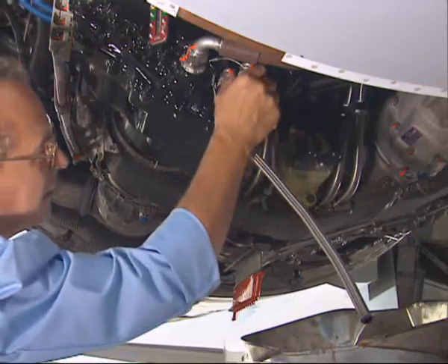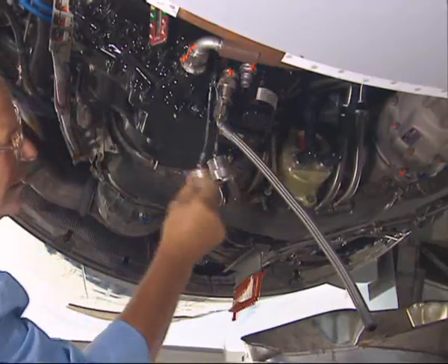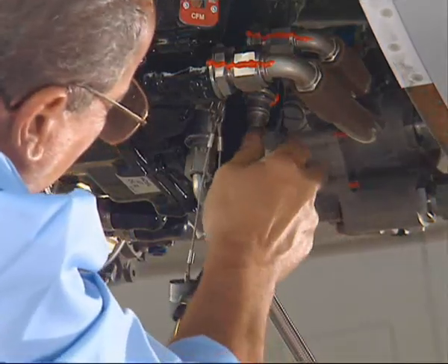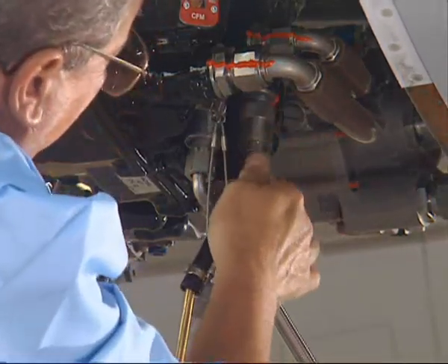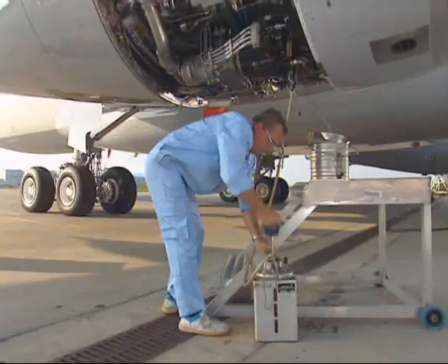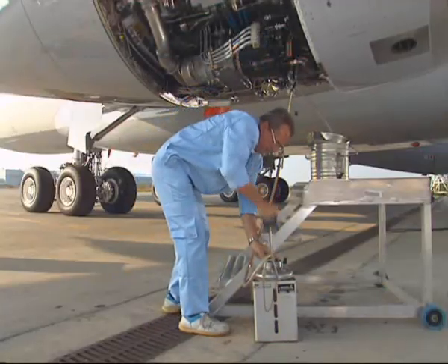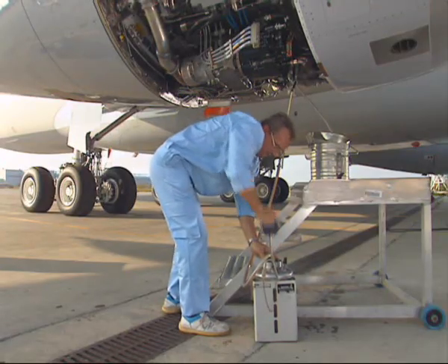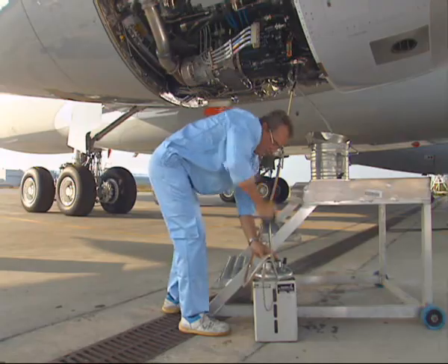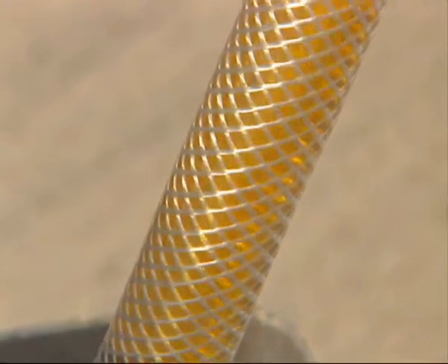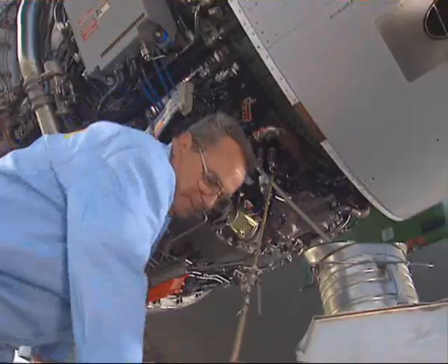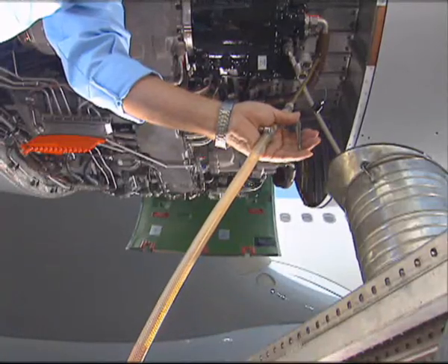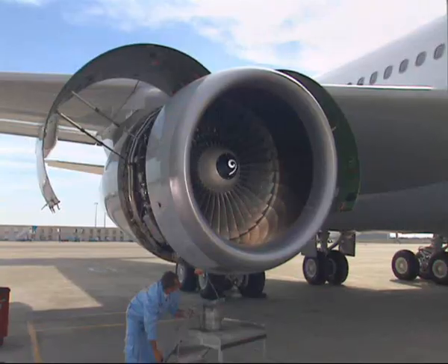Remove the dust cap from the pressure fill port. Connect the pump onto the pressure fill port. Fill the IDG with oil at a maximum of 35 psi. Ensure that there is enough oil in the pump reservoir in order to avoid the introduction of air in the IDG oil system. Use a transparent tube to control the condition of the oil during the IDG filling.